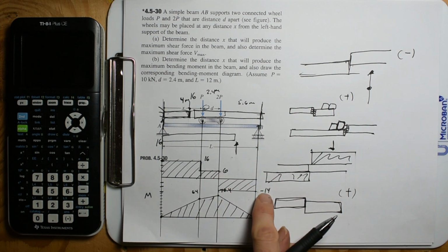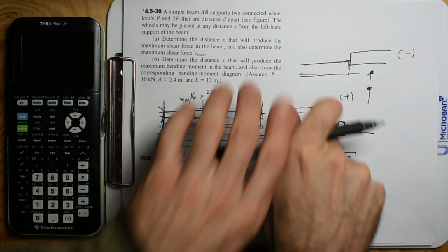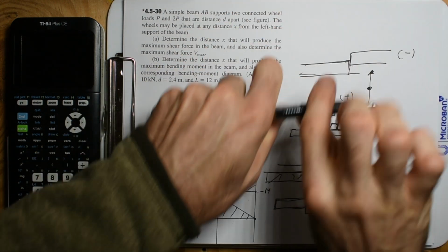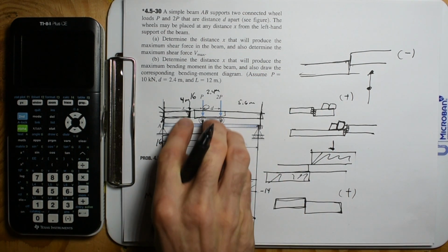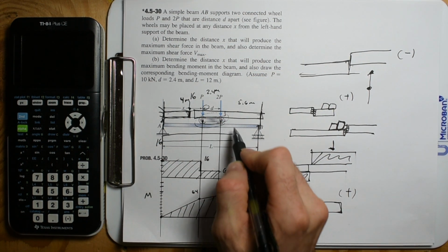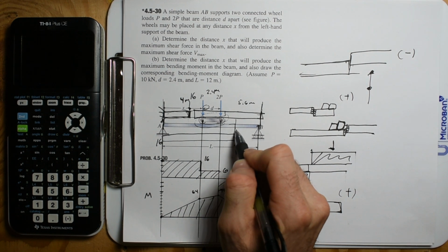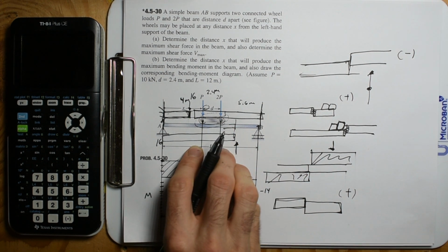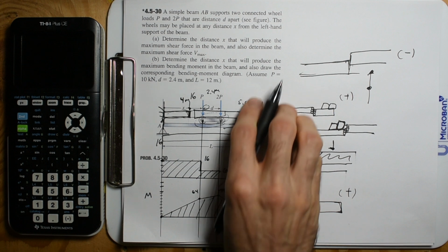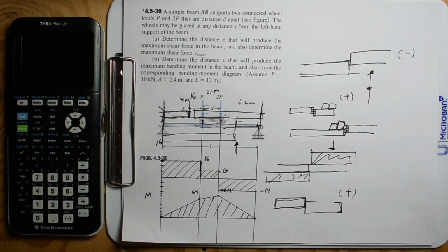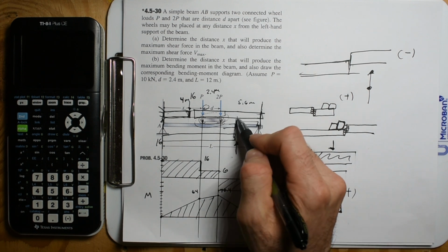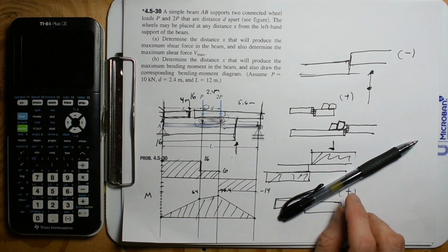So when we do have negative shear, that's going to be pushing up on this side. This side is going to go up and this side is going to go down, and hell yeah, because we got a heavy weight over there. If we take a cross section right there, this side is going to be more weighted, and this side is going to split up like that. You're going to have a fracture like that. If you're going to have a fracture, it's going to be in that direction.